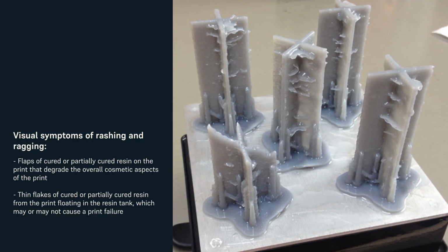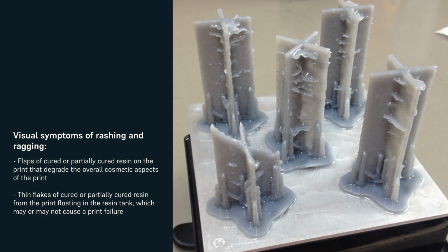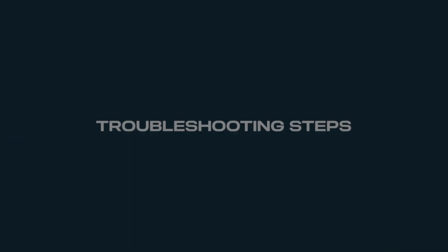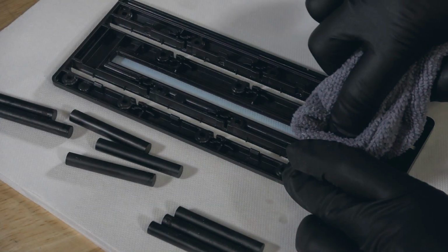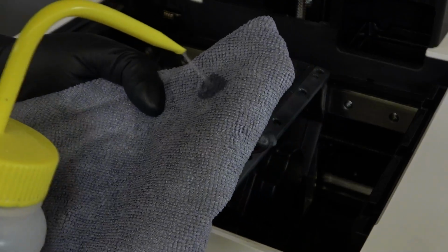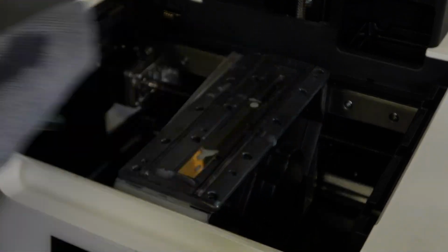If the UV light is diffused rather than blocked completely, the printer may have difficulty accurately curing the perimeter of each layer. The common factor tying these print defects together is that they can all be caused by something blocking or weakening the printer's UV light before it reaches the liquid resin in the resin tank.